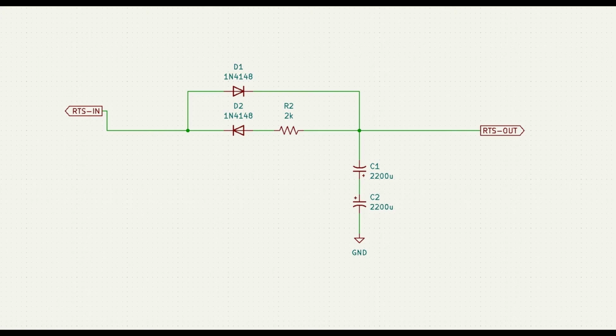All right, so the whole project here is to create a circuit that will, when I go to transmit, as quickly as possible assert the RTS line and get the modem operating. And when the modem starts generating audio, the transmitter will switch from receive to transmit. We want that to be delayed as little as possible.